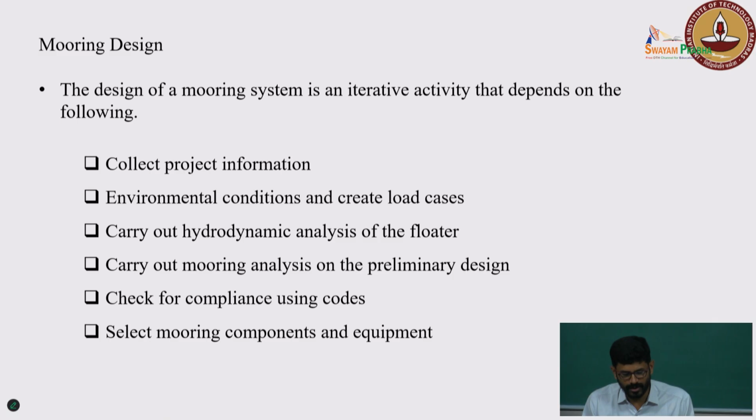And also we carry out hydrodynamic analysis of the floater, because, for example, you have a floater which is going to have a natural period matching the site natural period, right? The site's most probable wave period. Let us take for a given site you have a most probable wave period as 15 seconds, and if your floating body natural period is also 15 seconds, right? Then they will always be in resonance, right?